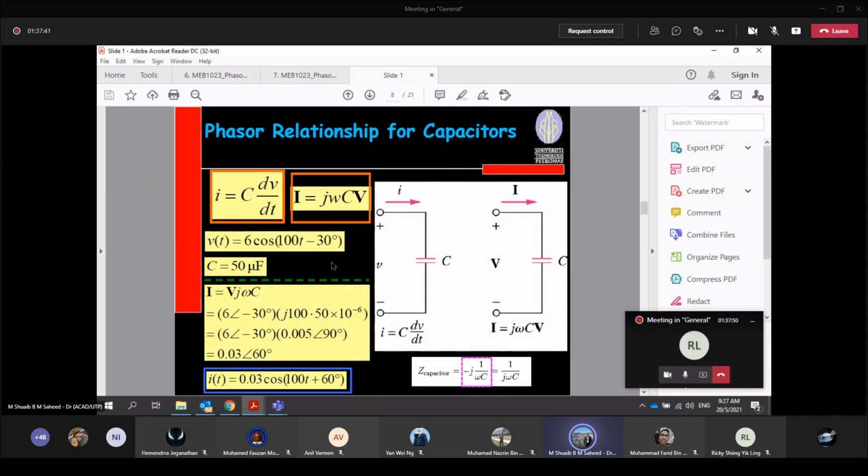So you have to find your XC first. So what is XC? Negative j over omega C. So what is your omega? 100. C is 50 micro. So you just multiply it, and then you plug into your Ohm's law formula.